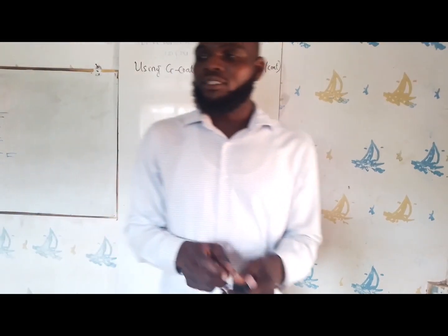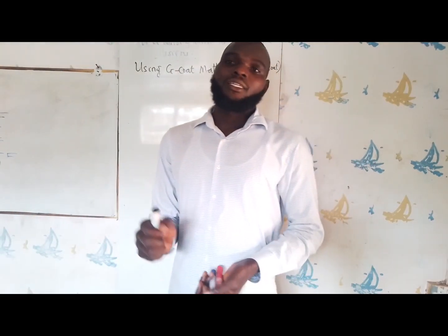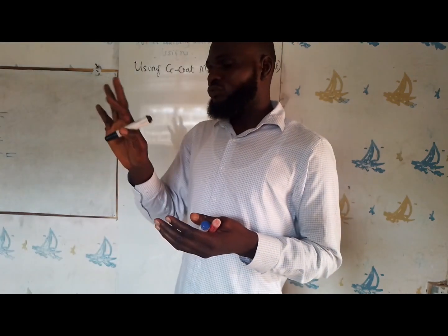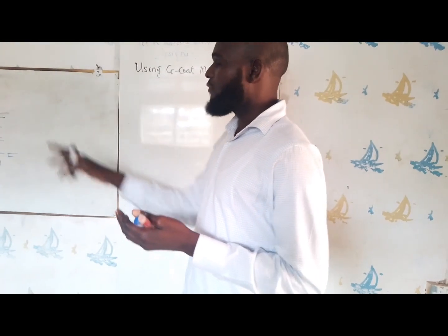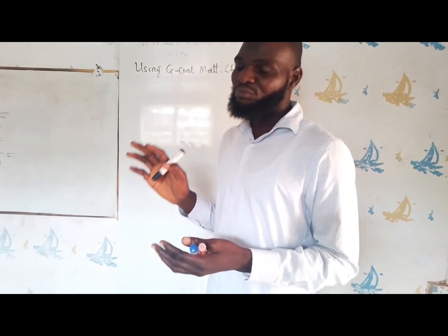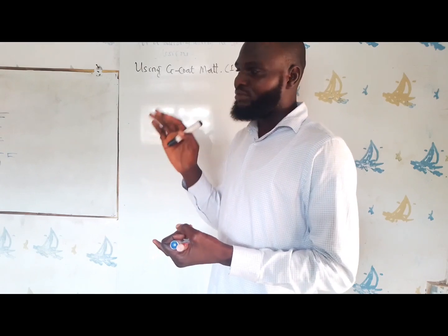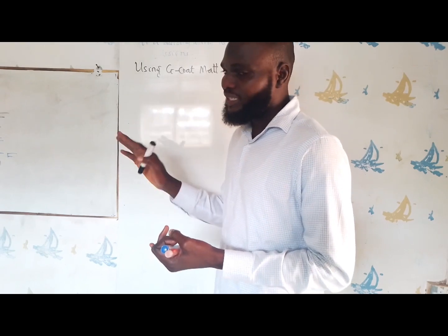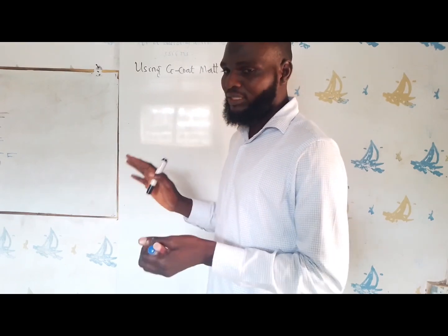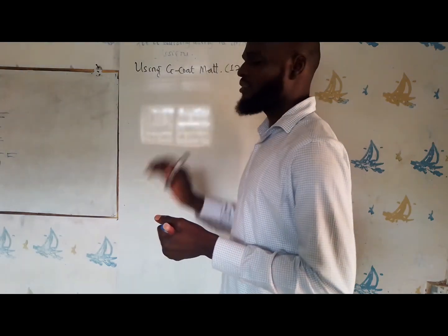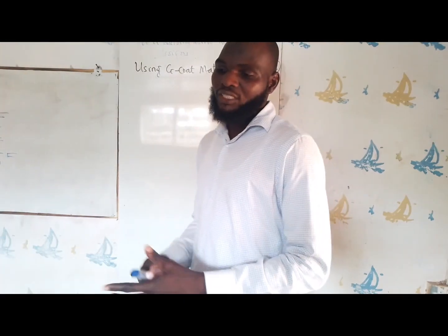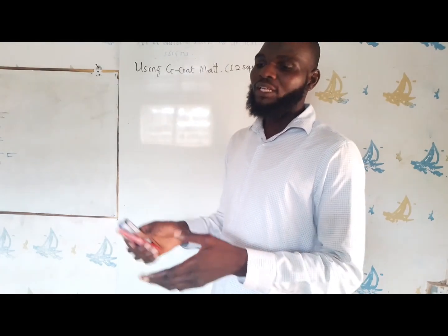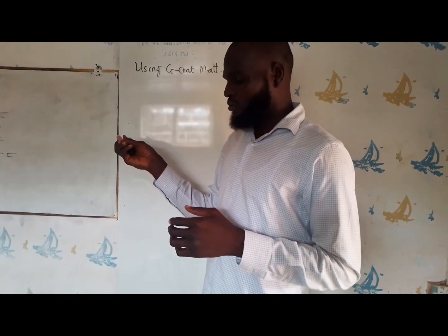So the meaning is that when you take a liter of our G-coat matte, it will cover an area of wall that has been sealed, meaning it has been prepared, it has been potted or screeded, sanded and primed. That is the meaning of a sealed surface. Now let us go to the areas we want to paint. How many coats are we giving? Before that, we have our drawing, which we show to you now.